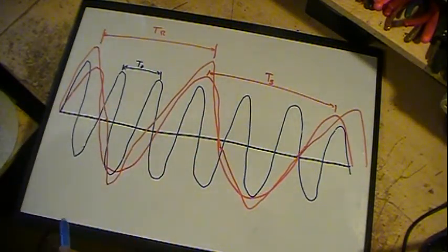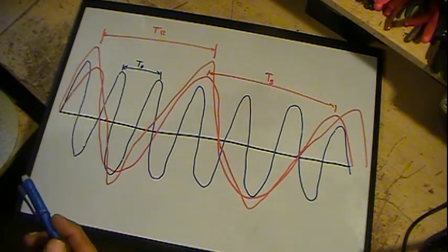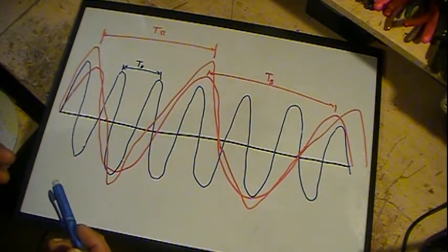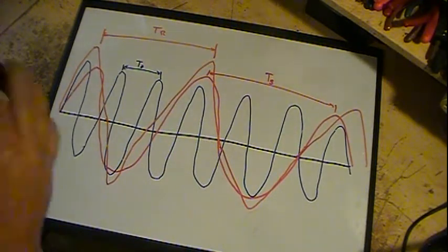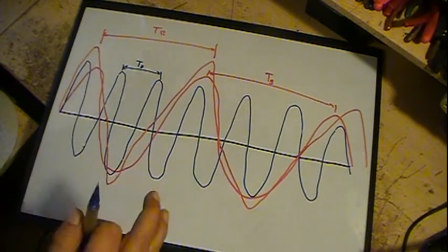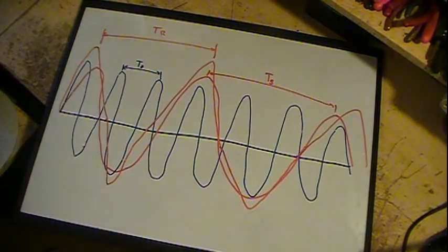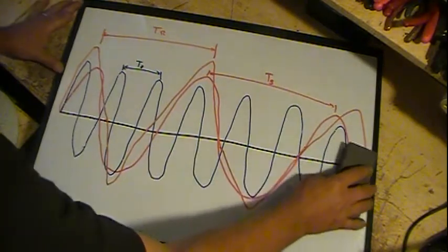That's how it works. Now the IF can is the guy that's going to figure out what to let through and what not to, and it's set at 455, so it's only going to allow a 455 kilocycle signal to get through. It'll stop everything else. So I hope that answers some questions on that. Now we'll try to look at what the other one's doing in a very simple way.